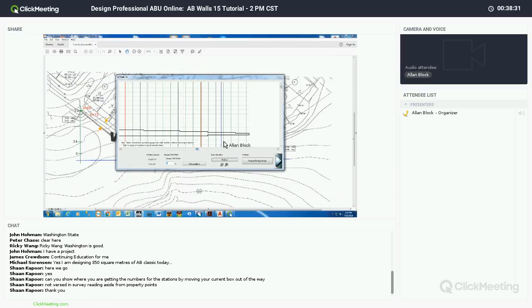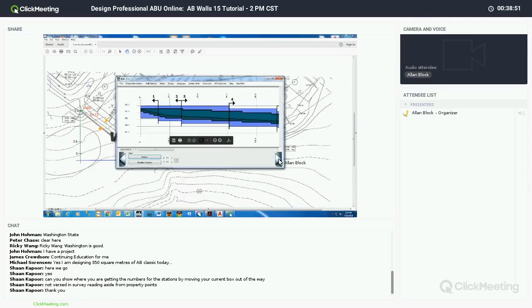Last one. All right. So once you've paneled out your wall, and again, if that was confusing for you and you have your own project you want to do, feel free to give us a call. Once you're done paneling out your wall and you're happy with how you've chosen it, you can hit the Finish Paneling button or the big blue arrow to the right. It does the same thing, and it's going to take us to the next page, which is our panel summary page.